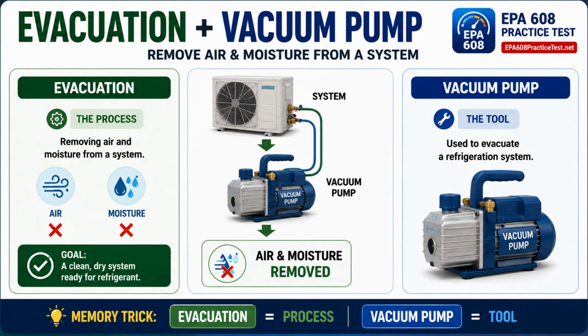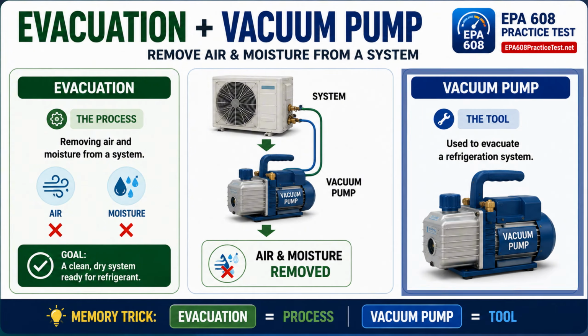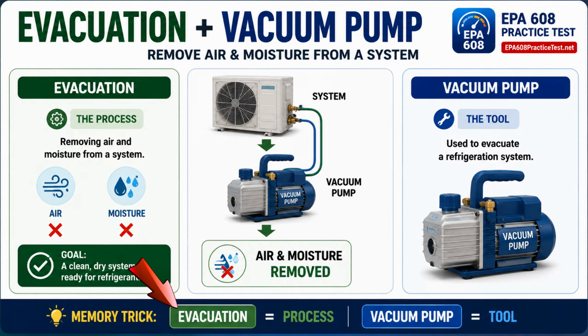System service. Evacuation is the process of removing air and moisture from a refrigeration system. To perform evacuation, technicians use a vacuum pump. The goal is a clean, dry system before refrigerant is added. For the EPA exam, remember, evacuation is the process. A vacuum pump is the tool.